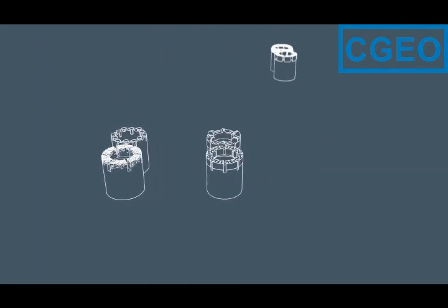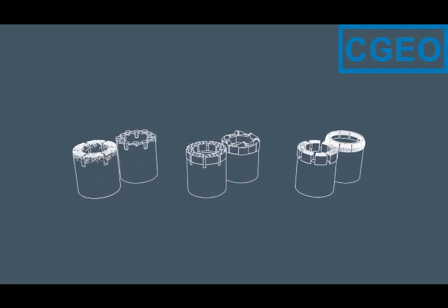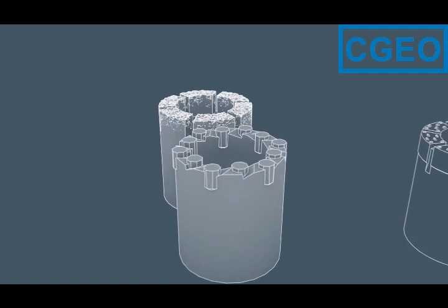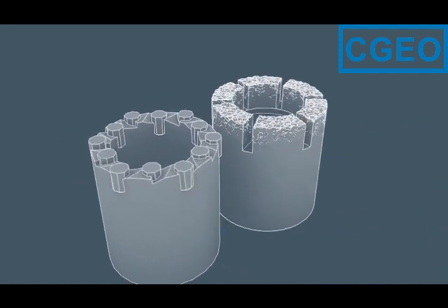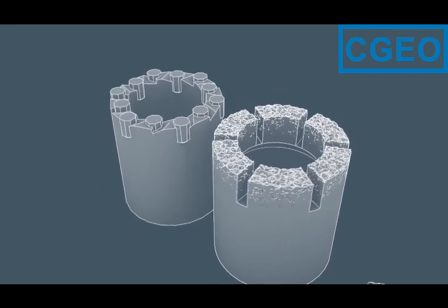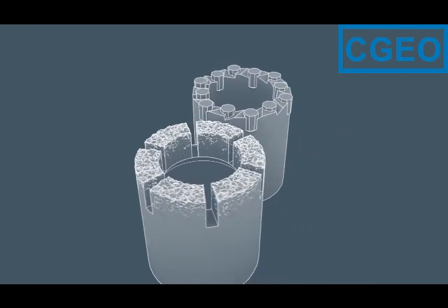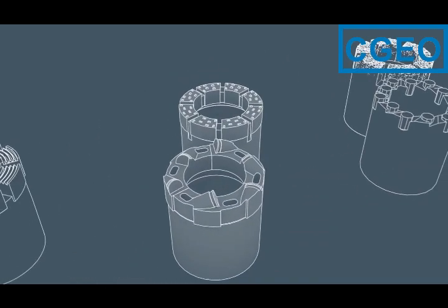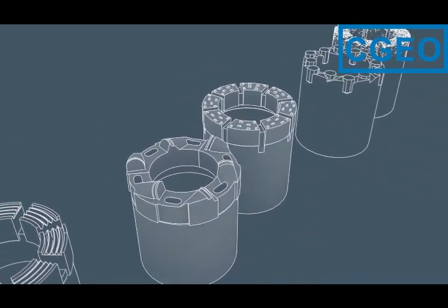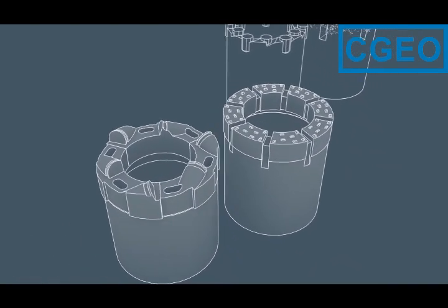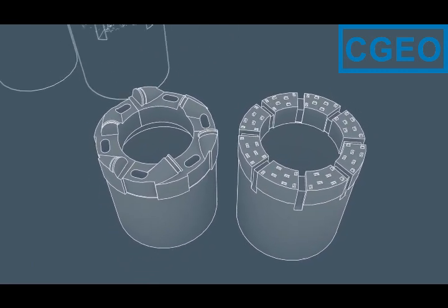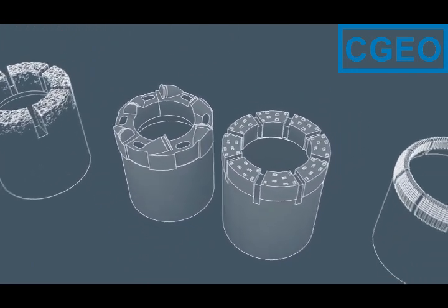The drill bit cuts out the actual core, and there are 3 general types, each corresponding to a certain ground condition. Tungsten carbide bits for geotechnical investigation core drilling in soil and in other soft formations. Tungsten carbide is used in the form of inserts, or chips. PDC, or polycrystalline diamond composite bits for core drilling in soil, soft shale, soft limestone, and other soft sedimentary formations. PDC bits are used in the form of buttons, or surface set.